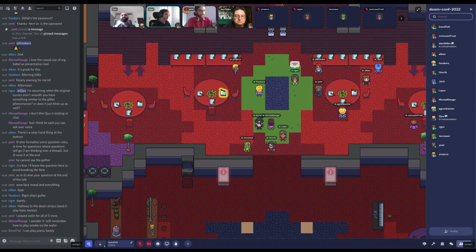Is there some sort of rule of thumb to how much you should discretize with respect to the system that you're trying to simulate? Yes and no. It's very, very problem specific. If we take something like this pipe flow, we can get away with very coarse resolution. If you have a shock wave, you need very, very fine resolution near the shock wave, for instance. So it depends on the physics and how fast the physics translates.